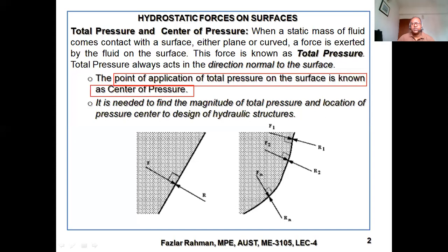Right over here, you see a curved surface in contact with a fluid. So what will happen? The fluid pressure at every point will be perpendicular to the surface. Gradually, as you move upward, the pressure will decrease from the surface.